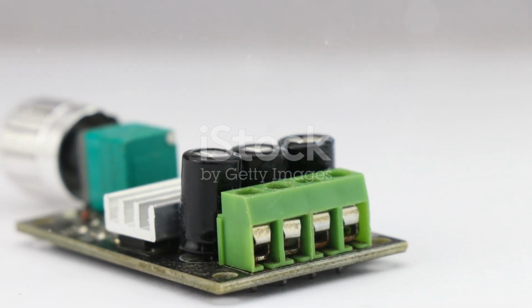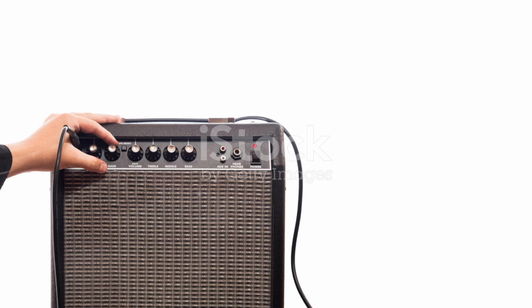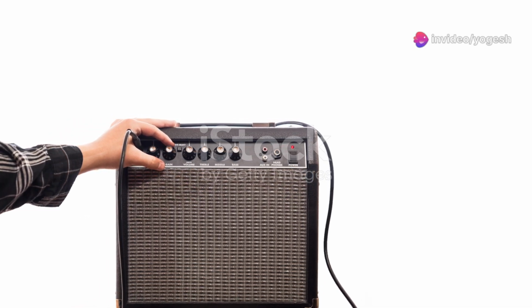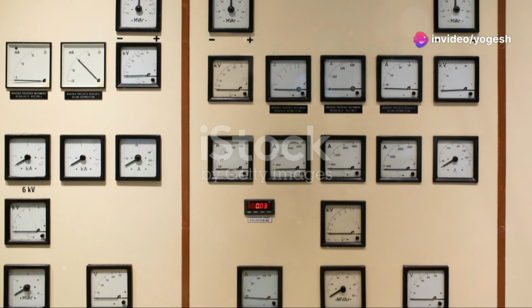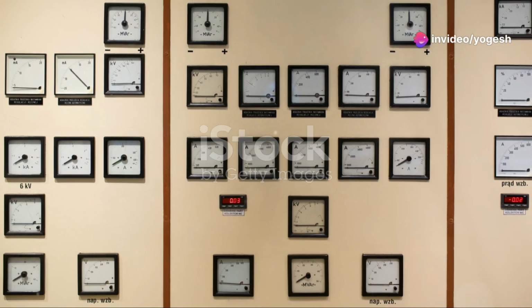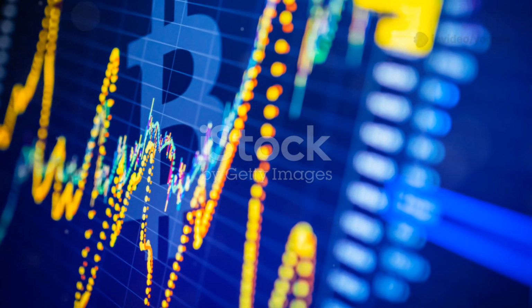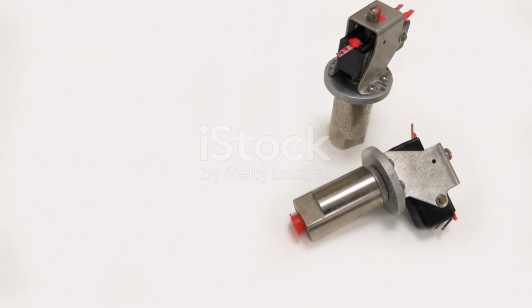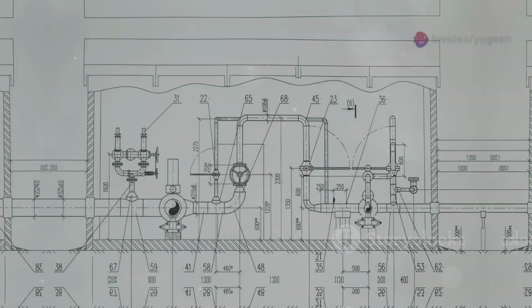It provides an immediate reaction to any deviation. The strength of this reaction is determined by a gain factor, Kp. A higher Kp means a stronger reaction to the error. However, a Kp that is too high can make the system unstable. It might oscillate wildly around the set point.